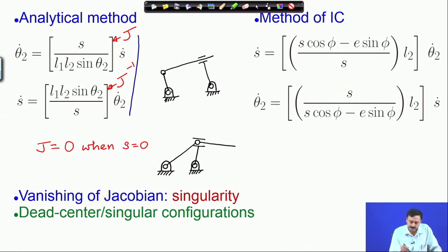So, from here if I start moving, of course, the link lengths look a little different. When I start rotating the link 2 in the clockwise direction, there will come a situation where this revolute pair will start going into the prismatic pair.